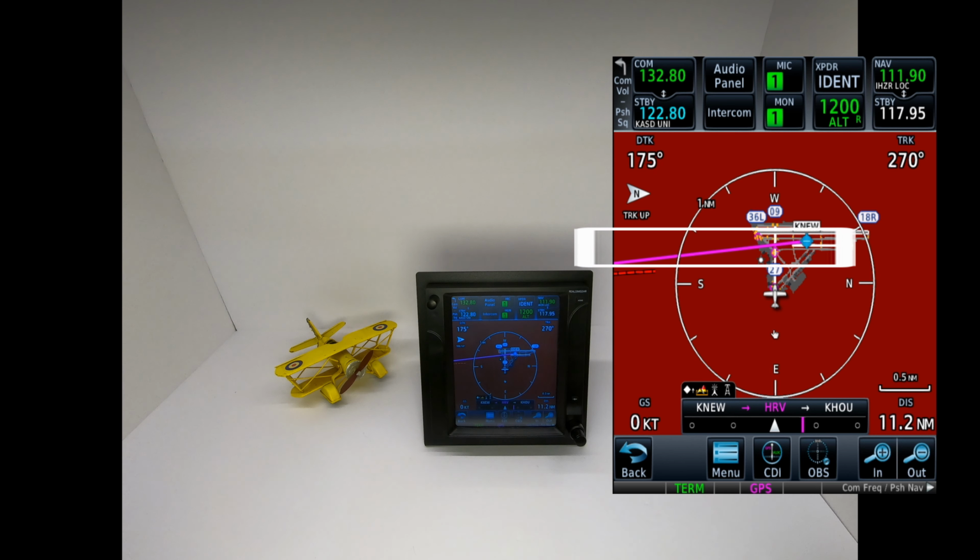And there you go, you see how the magenta line went back to Lakefront Airport. This is useful because whenever you fly, especially in VATSIM or something, ATC might tell you to fly direct to, say, Harvey, and then you can just do direct to, and it will take you straight into it. Or say that you had to deviate a little bit because of traffic, weather, terrain, or something, but then eventually you just want to follow the line that you planned.